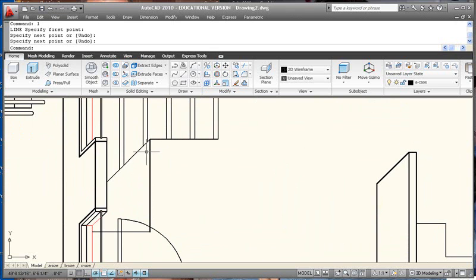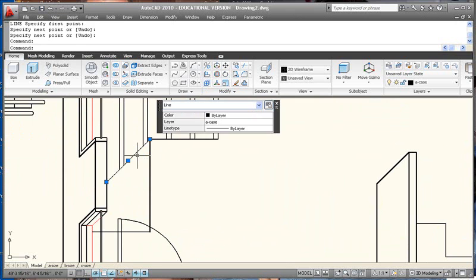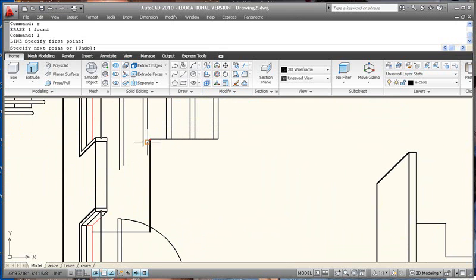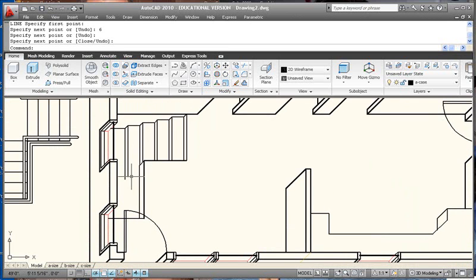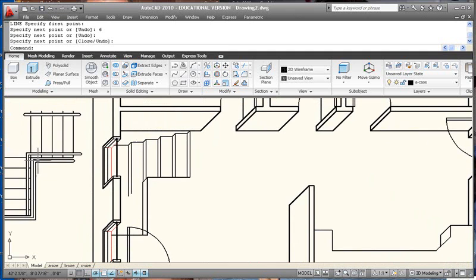The floor thickness is usually only about a foot thick, so we're going to get rid of this line and draw another line from that corner down 6 inches and then come across. And this line here should, we should be representing the tread here as the same width that we have it set up for the stairs. So I should be able to take these lines here and offset them 3 feet.